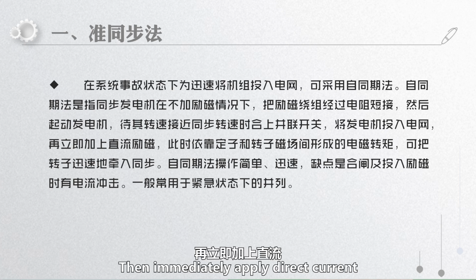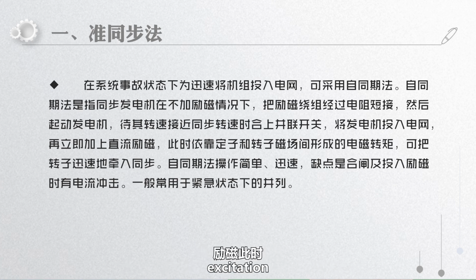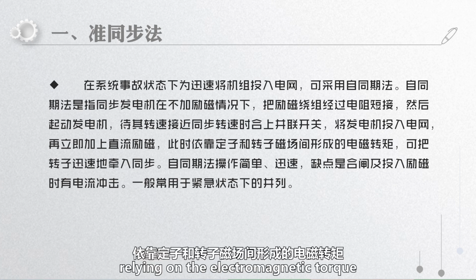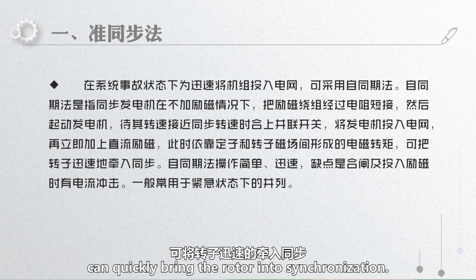Then immediately apply direct current excitation, relying on the electromagnetic torque formed between the stator and rotor to quickly bring the rotor into synchronization.